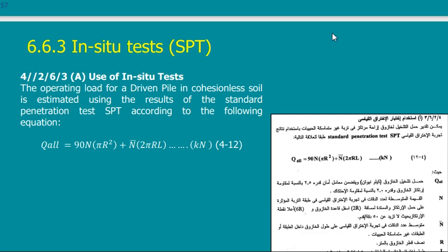He will go outside of the site, next to it, construct a similar pile, and will load this pile, take the chart for the loading and the settlement, and from this, it either proves my design or tells me that my design was not correct.